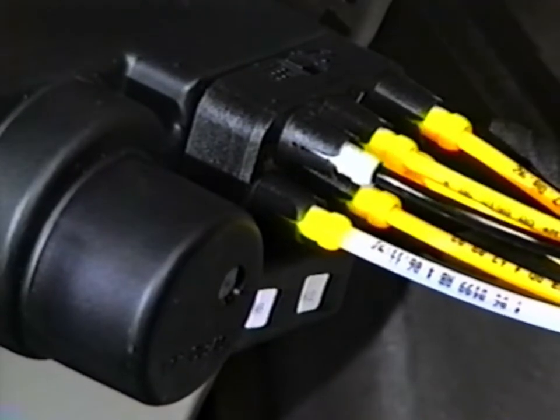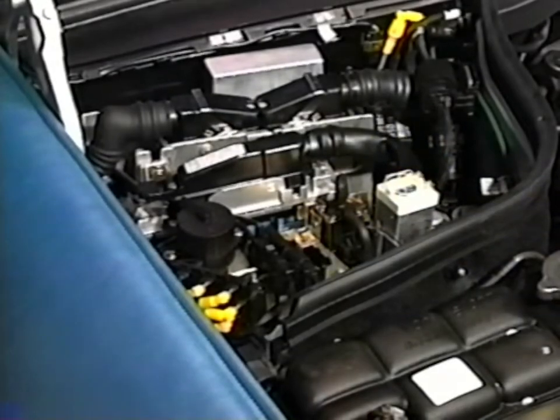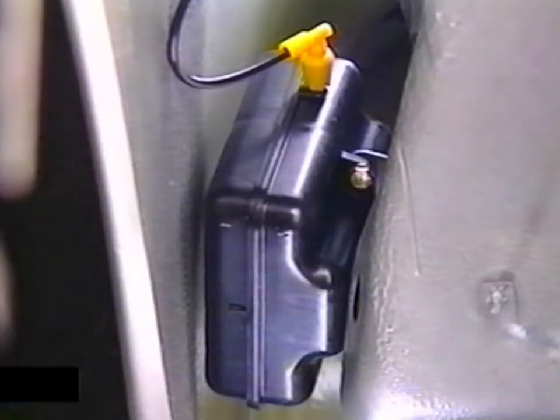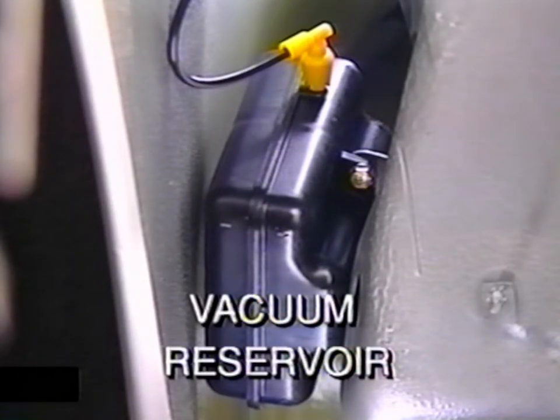A transparent line from the trunk delivers vacuum to the distributor block, which serves to maintain vacuum in the air conditioning vacuum reservoir if the engine vacuum is insufficient. The air conditioning vacuum reservoir is mounted in the right front wheel housing.